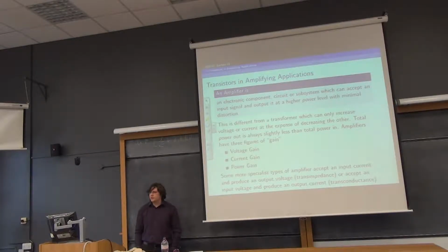The amplifier is different in as much that the signal going in has less power, or can deliver less power to a set resistor than the signal coming out. And the way that we achieve that is essentially by modulating the DC power supply which the transistor is running off. So what we're doing is we're taking some energy from the DC power supply and using it to drive the load. So there is a certain amount of detachment between the input and the output.